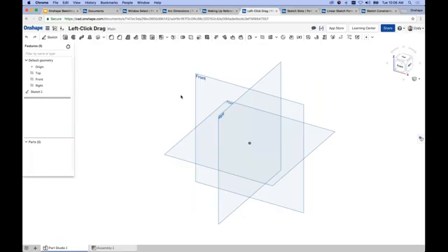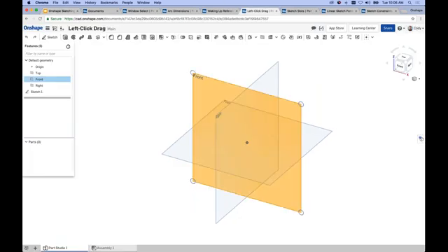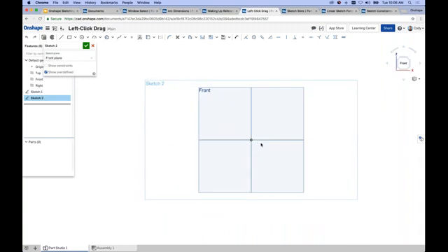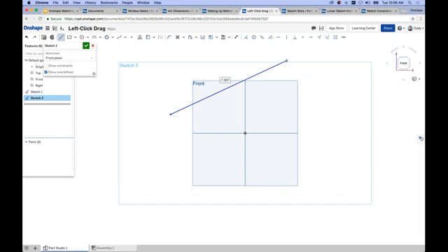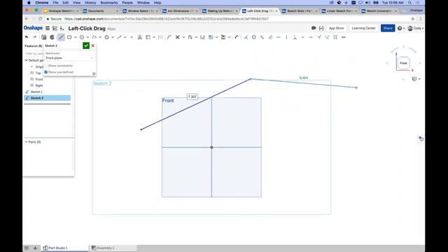Let me jump into a document here. This is just a blank sketch. And what I'd like to do is start with the most basic of those tips, and that is just the line example. So by default, many new users and many experienced users as well will use the two-click method for creating lines, right? That is left click, and you have your line, right? Now, by default, when you do this, it assumes that you want to continue on with another line. And so if that's the case, this is the tool that you'd want to use, because then I can go on, left click another time, and I'd have another line that's attached to my previous one. So again, a very important workflow for creating lines.